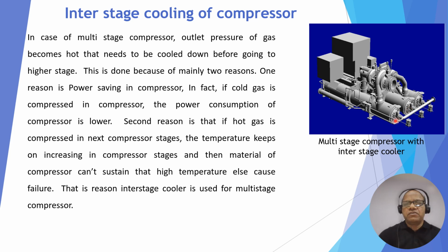So you see a lot of heat exchangers are given here. The outlet of one stage goes to a cooler, where the pressure drop is very small, but a temperature drop occurs, and then the high pressure cool gas goes to the next stage. Then why is it required? In a multi-stage compressor, the outlet gas becomes hot. You know that it needs to be cooled down before going to the higher stage of compression.